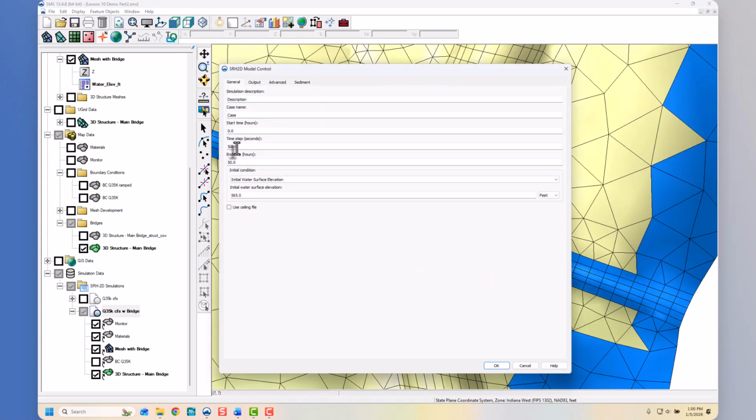And in this case, looking ahead, I'll save us some time. We do go into pressure flow in this simulation, and it does go a little unstable. So what you'll see when it tries to run the simulation is a red bar at the top, and it'll suggest a smaller time step. In this case, I've had to drop the time step down to 2 seconds.